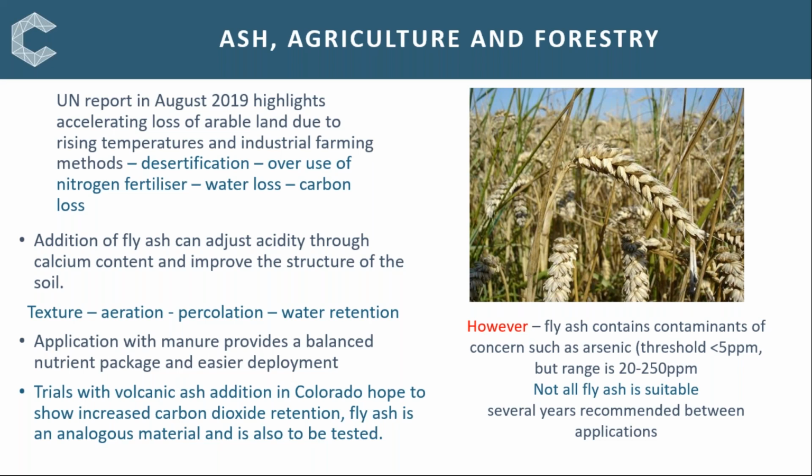The main concern, though, is that there are a number of toxic elements in fly ash, mercury and arsenic among them. If in moderate or low levels, these are easily accommodated, but some fly ash is inappropriate. Some guidelines suggest intervals between applications should be several years, and the loading rate should be modest. But this would ideally be supported by chemical analysis to confirm the safe use of ash in this application.